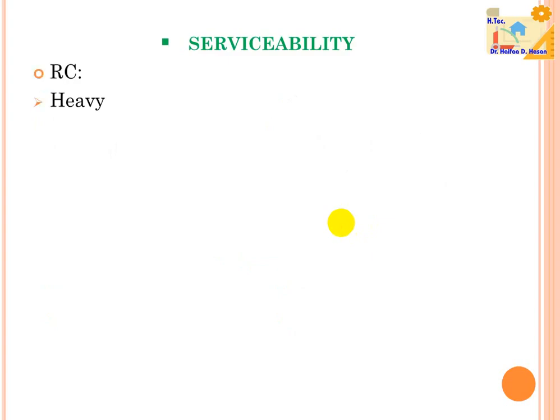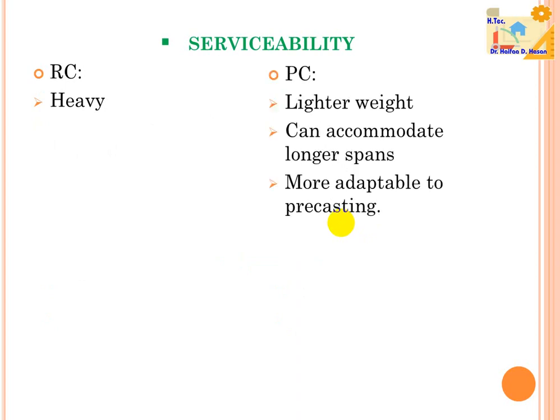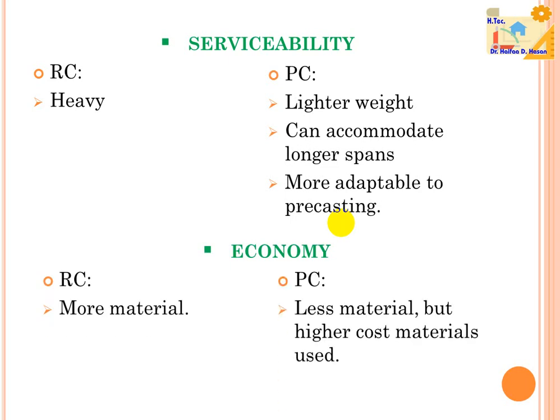Serviceability. Reinforced concrete is heavy. A pre-stressed concrete member is lighter in weight, can accommodate longer spans, and is more adaptable to precasting. Economy. Reinforced concrete uses more material. Pre-stressed concrete uses less material, but a higher cost material is used.